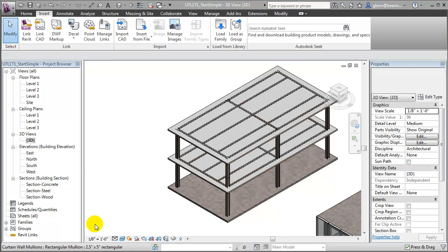The structural floor slabs are located at the correct elevation, but the beams and beam systems are actually protruding up through the floor slabs because they're located too high. Rather than placing beams and beam systems right at the floor level, we should take the thickness of the structural floor into account and lower the elevations of those beams and the beam systems. Let's look at how that's done.